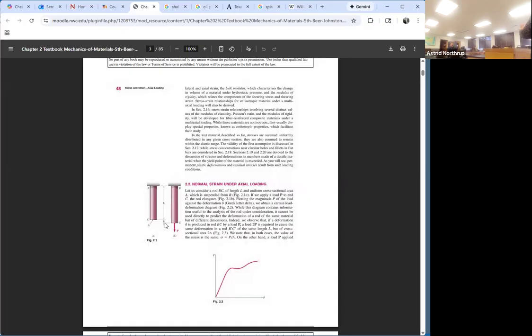Okay, when we talk about shearing stress, you talk about maybe taking something like this and putting it under stress, it's going to deform like this. And so the change in the angle from the original to the new angle is called gamma, which is a shearing strain. We're not going to mathematically do a shearing strain right off the bat, but in any case, strain is dimensionless, a fraction or percent change either in shape, in length, or in angle.